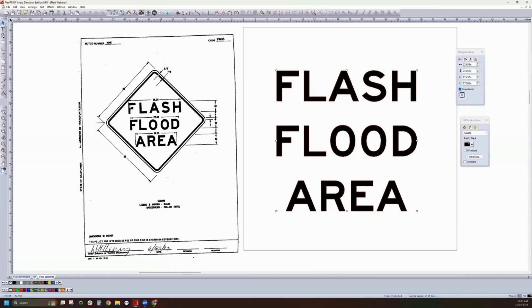It's saying that the distance between this F and the H is 26.3 inches, when in reality, and we'll see here in a minute, the 26.3 is actually the distance between the inside of the border on this sign at that level when you have this centered, which becomes a problem because the letters are touching the edge of the border, and that poses an issue with legibility because there's not a break between the border and the text.